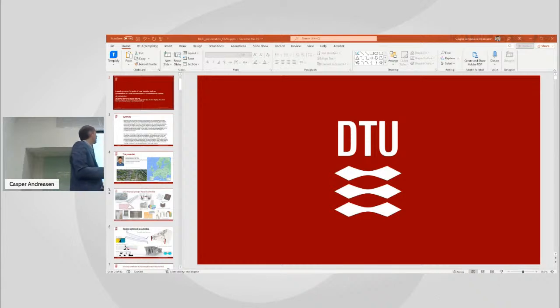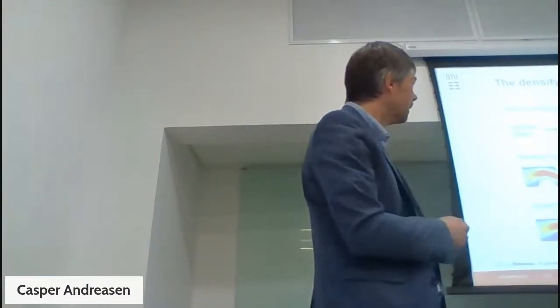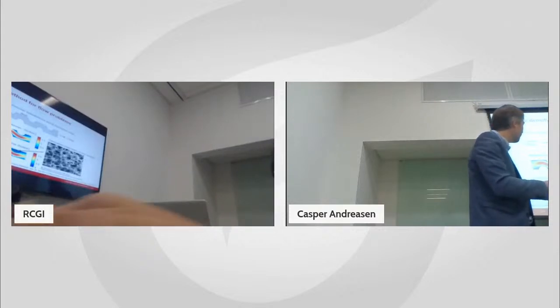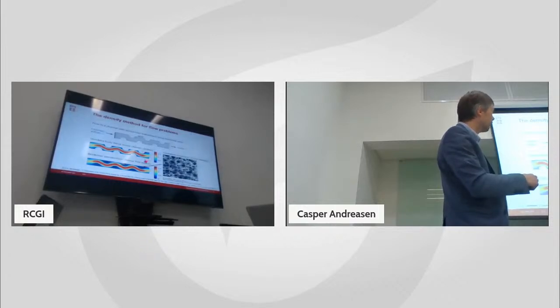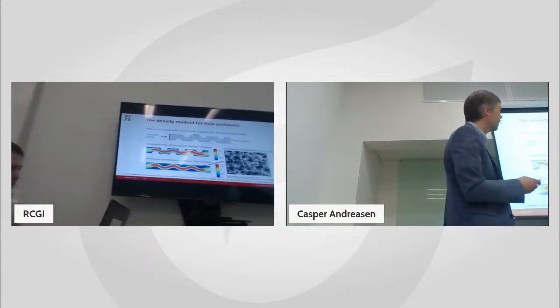I'd like to look at it in a bit different way, that if we would like to solve the flow problem in such a structure like this, we would think of a generalized porous medium approach. So you would basically either model it with a body-fitted method, right? But we are interested in trying to be able to modify these indents. So by filling in a porous medium, we are able to mimic the flow domain and then introduce a solid medium in which the fluid does not flow, or at least is very limited in its flow. So you could think of it as a generalized porous medium.